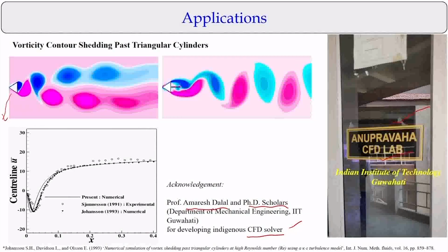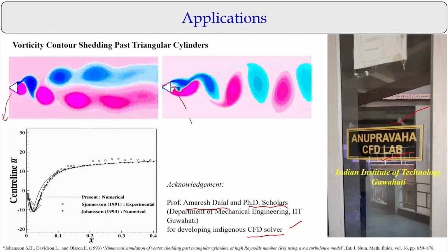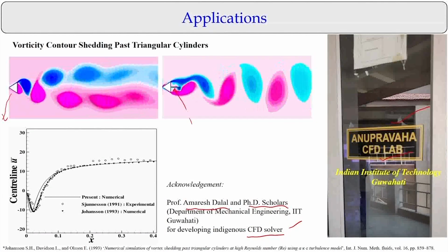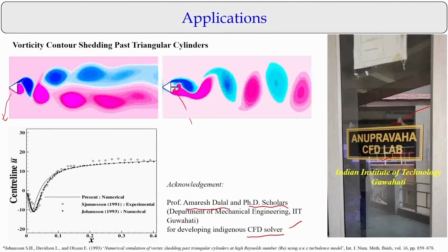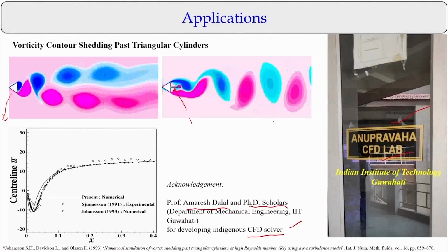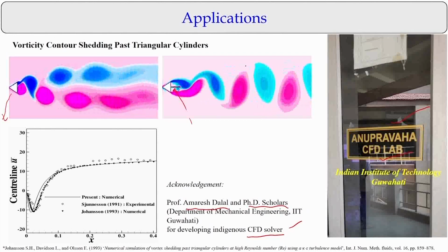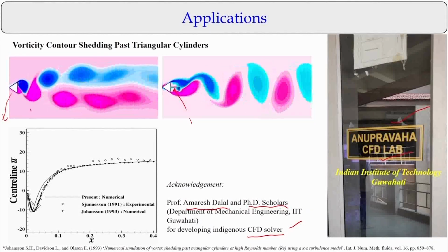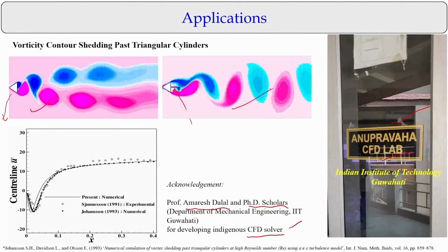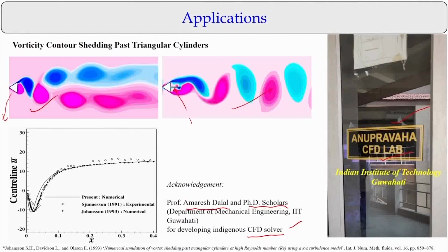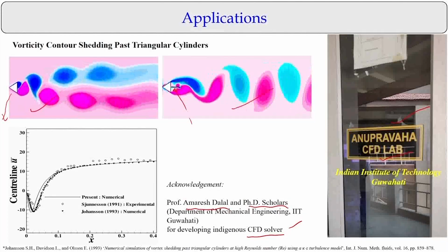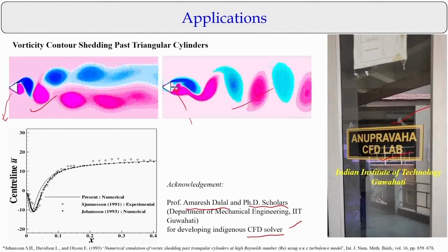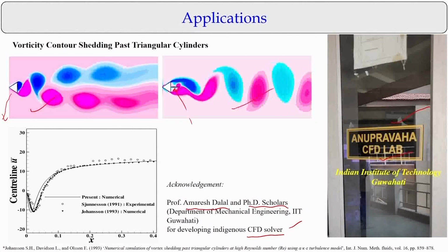But if you include one small thread, the flow pattern changes. If you look, there is such a simple thread, and the flow pattern that results is very interesting. The flow pattern of this one and the flow pattern here differ. The streamline patterns, the streak line patterns and the path lines will differ, and there are vortex formations. The series of vortex formations moving downwards is called vortex shedding.